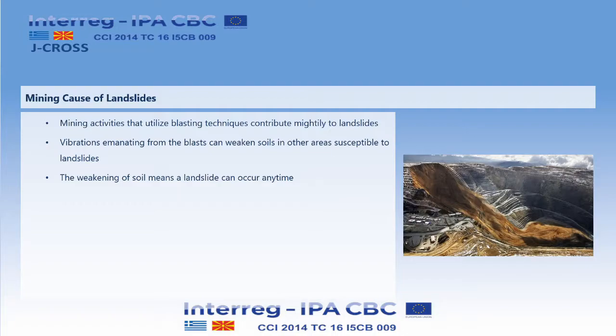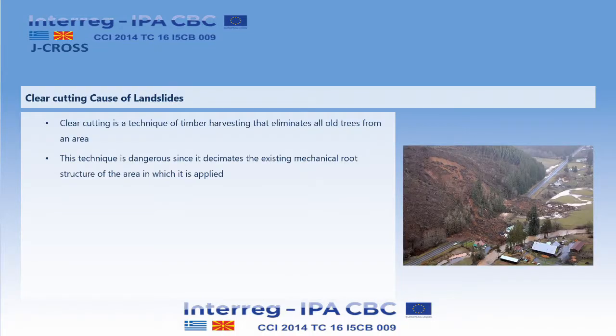Mining activities that utilize blasting techniques contribute mightily to landslides. Vibrations emanating from the blasts can weaken soils in other areas susceptible to landslides. The weakening of soil means a landslide can occur anytime. Clear cutting is a technique of timber harvesting that eliminates all old trees from an area. This technique is dangerous since it decimates the existing mechanical root structure of the area in which it is applied.